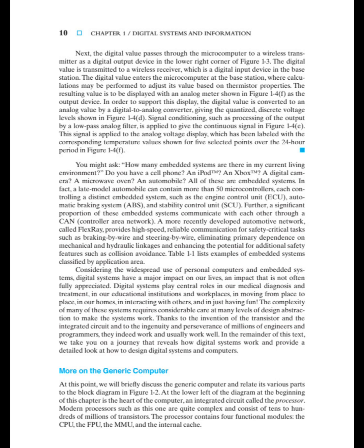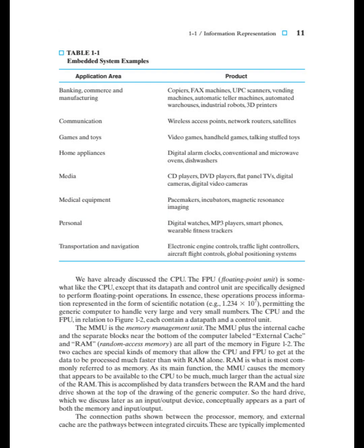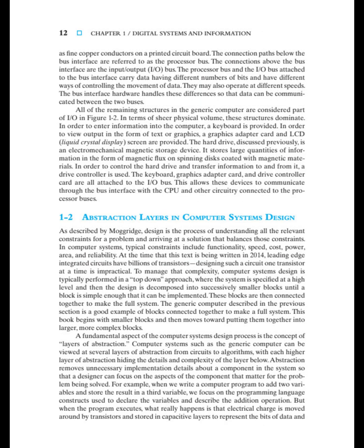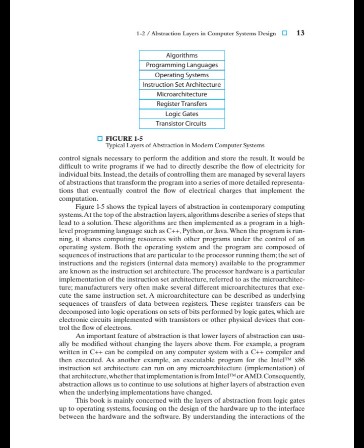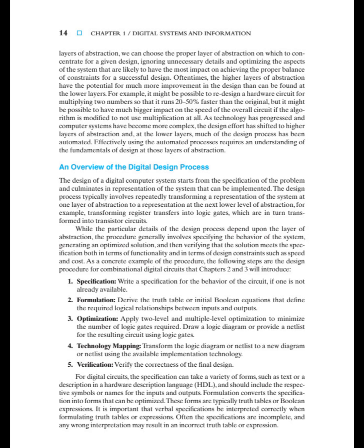One simple method is using a parity bit. This is an extra bit added to a code word. It's set so that the total number of ones is either even or odd. Then, when the data is received, the parity is checked. If it doesn't match, you know there's been an error. A basic error detection mechanism. It is. And finally, there are gray codes.